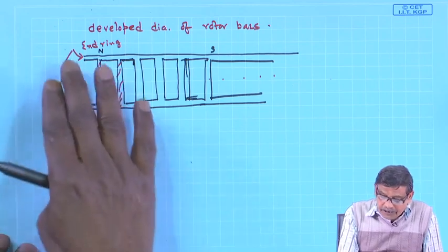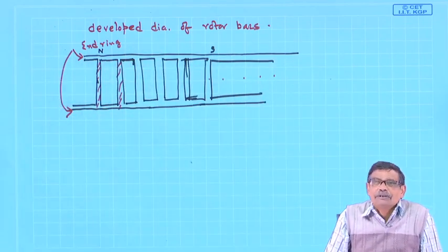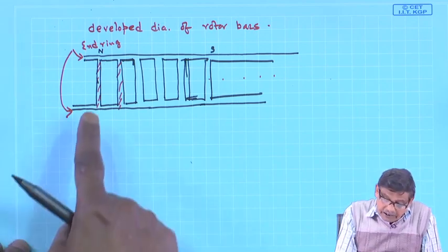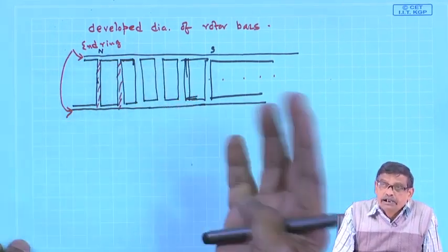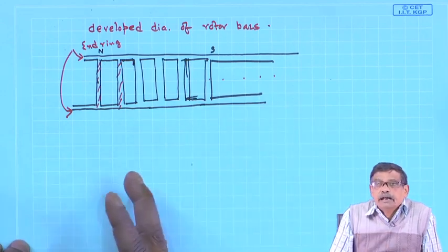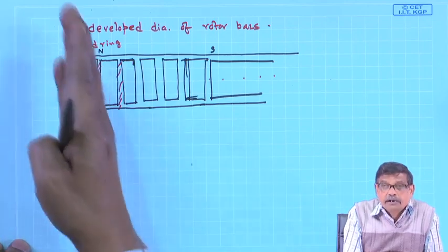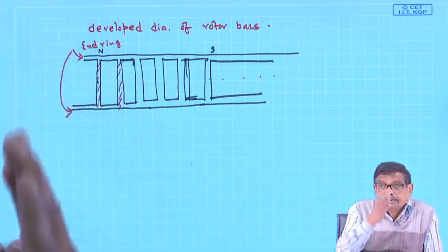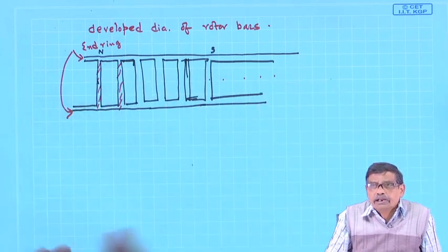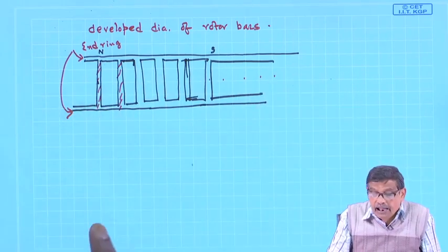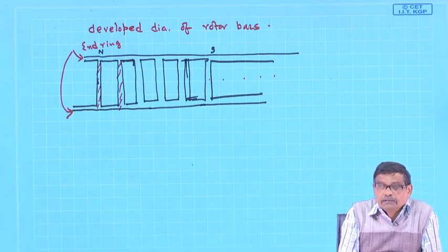That is the beauty, it is already shorted, but in slip ring induction motor, that is not possible, because the return conductor of a particular turn is already decided by me, and I have taken all the care that if one coil side is under the center of the north pole, generally the other coil side will be under the center of the south pole, and they have got their own identity, a separate coil.